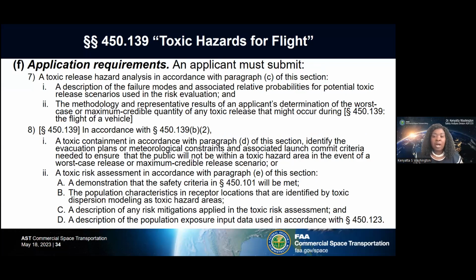The application requirements also include a toxic release hazard analysis, including, I mentioned that before, a description of the failure modes and associated relative probabilities for potential toxic release scenarios used in the risk evaluation, and the methodology and representative results of an applicant's determination for the worst case or maximum credible quantity of any toxic release that may occur during the operation.